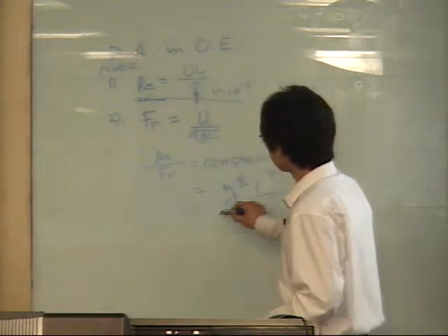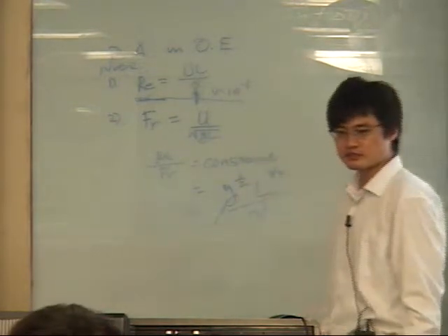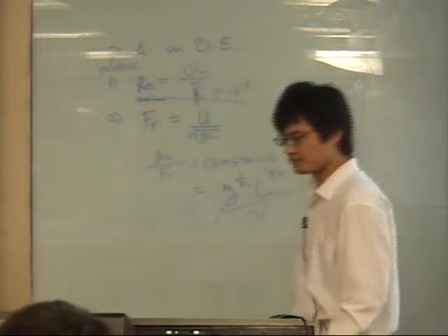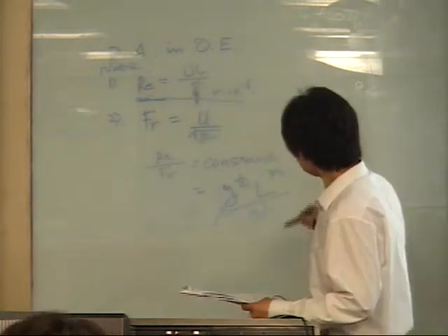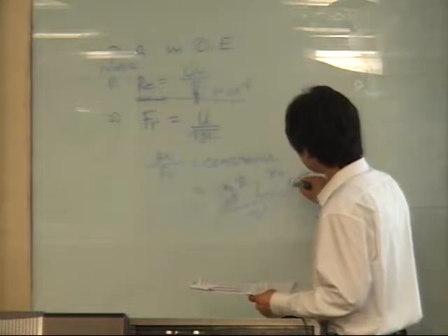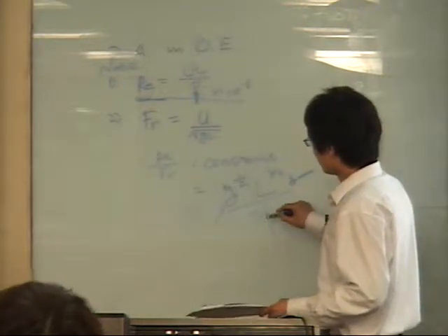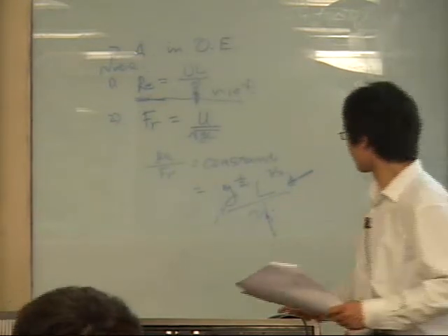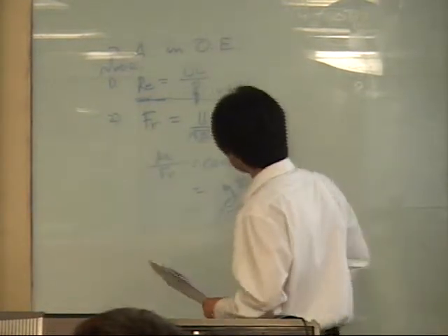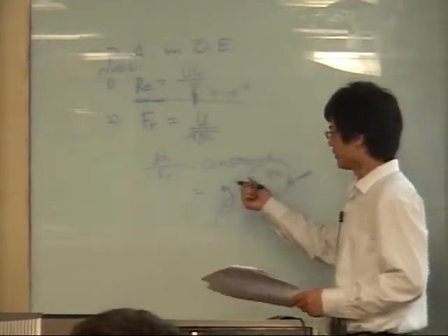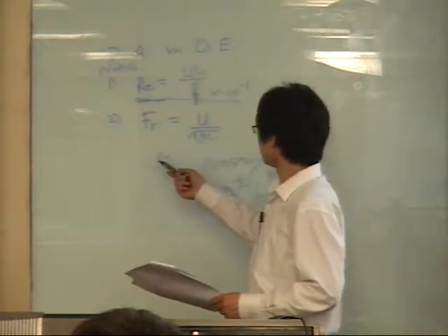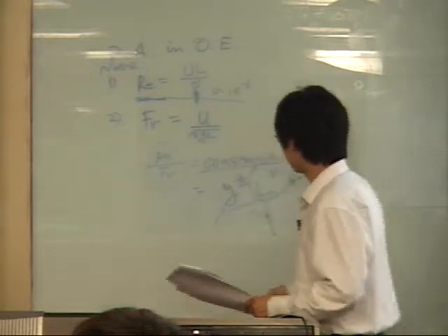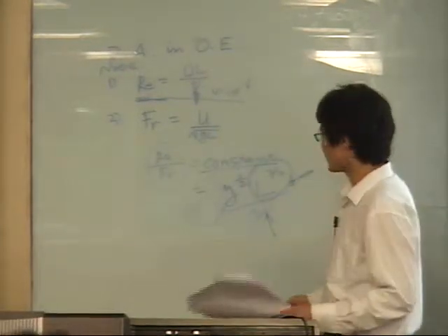We know g is not changing, right? This gravitational acceleration, if it changed, we'd have trouble. And the length can change. Viscosity for water, it's probably not. So we have a non-constant here. So we have no way to achieve this condition for a test in water, in reality.